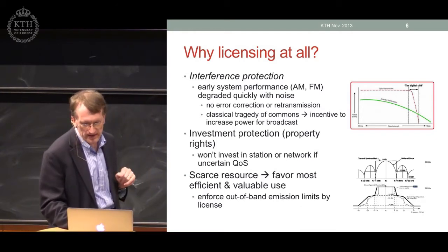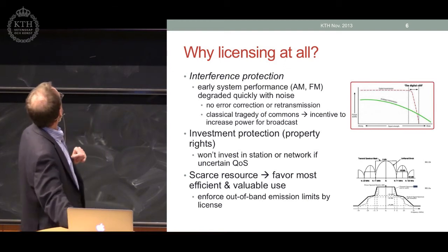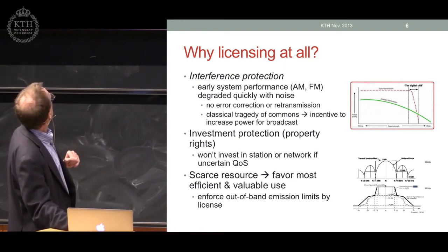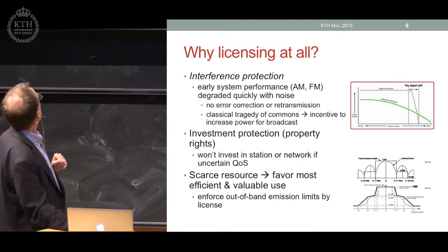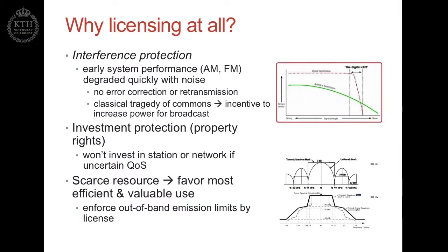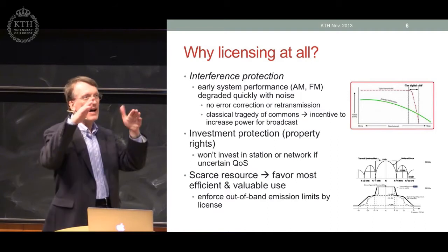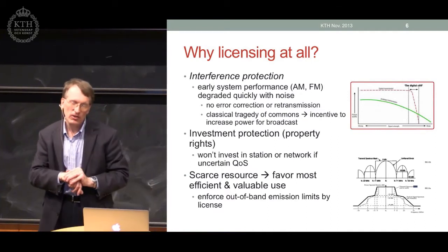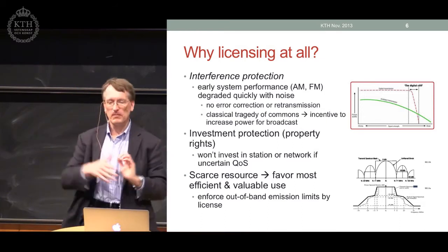If you look at, for example, this Wi-Fi picture here, you can kind of see that you have a main lobe of a transmitter, and then you have side lobes which are just naturally caused by the system design. So the rules, for example, for radio transmission are such that you are supposed to transmit at full power, and then you have to roll off. You have to protect your neighbors who are in that area already against what's called out-of-band emissions, because you just can't physically, given real filters, have a filter with a nice rectangular shape. They have a slope.